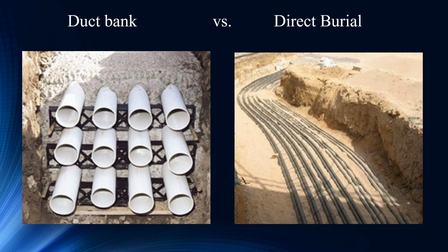The concrete helps protect the conduits or cable from any moisture in the soil, which in turn prolongs the life of the material. The conduits, apart from helping properly space and separate the cables, also facilitate the cable pulling process, as well as allow modification and easier fault localization than their direct buried counterparts.